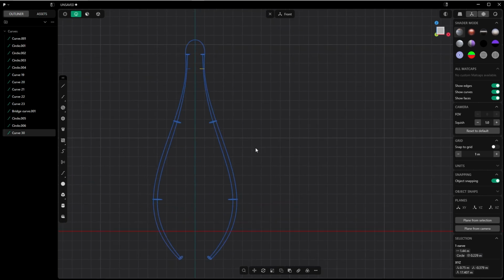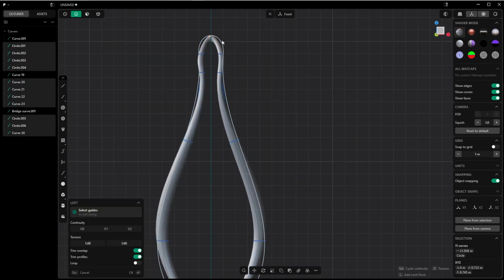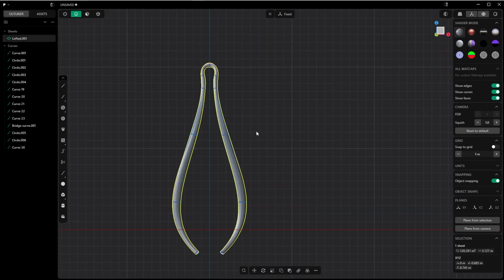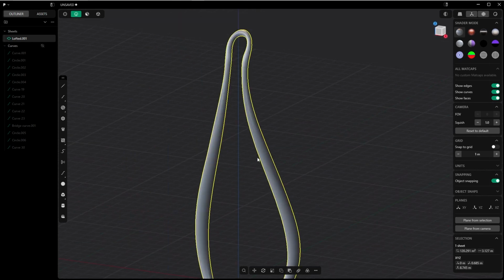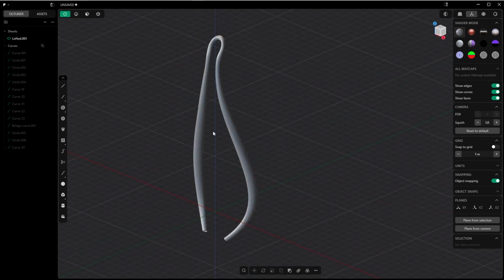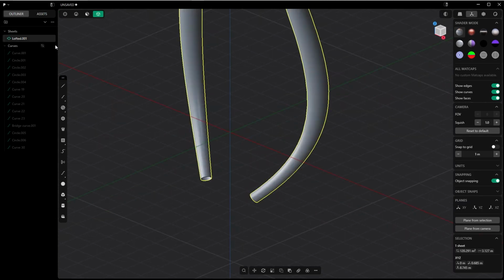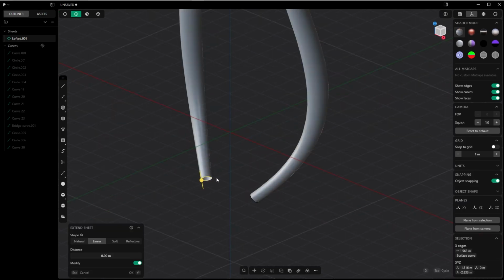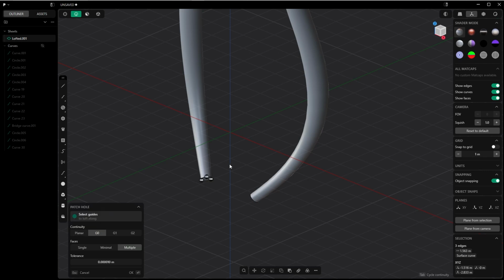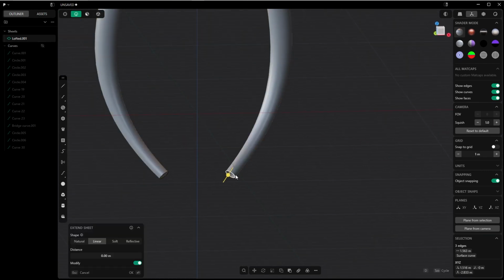And again, repeat the loft. And select the guiding curve. Yeah, and this one looks better. And I press OK. Now I deactivate the curves and I create an isoparam curve. But before creating an isoparam curve, let me first convert this sheet into a solid by closing these holes with Shift J, G0 continuity, and here as well.